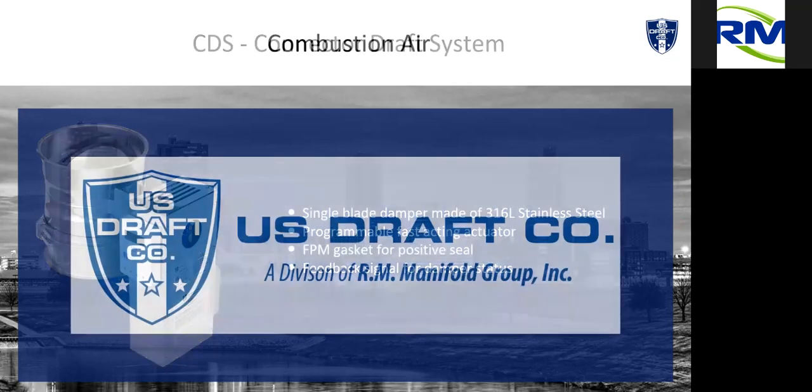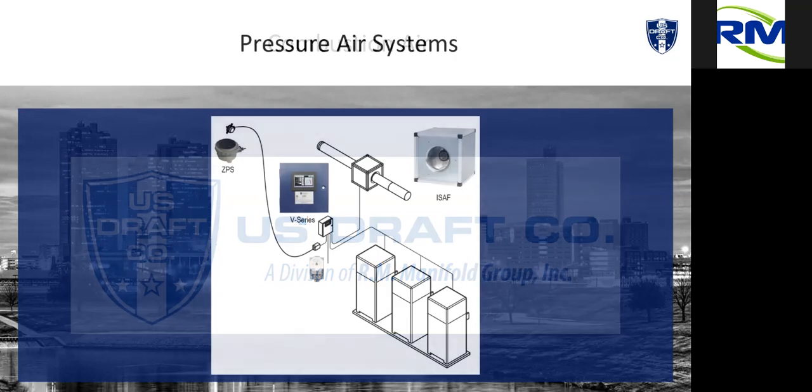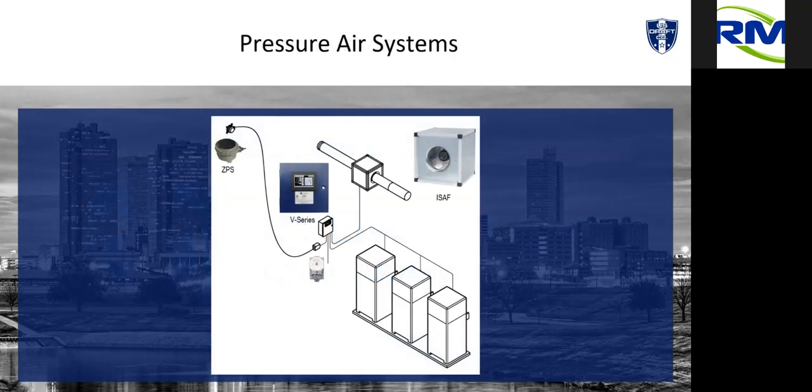Real quick, I mentioned combustion air. When everyone talks about mechanical draft, and they think about venting, and they think about getting the exhaust out of the appliance, the most important thing is getting air back into the space, or getting air into the appliance. And so we offer what we call our pressure air system. This is a modulating combustion air system.